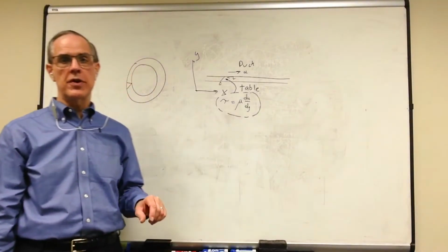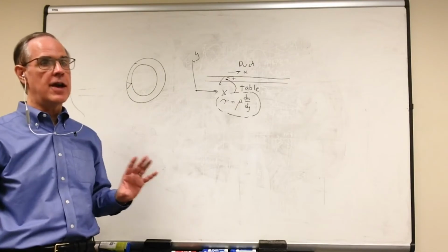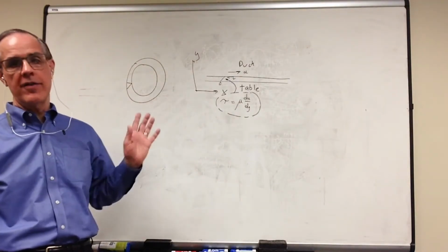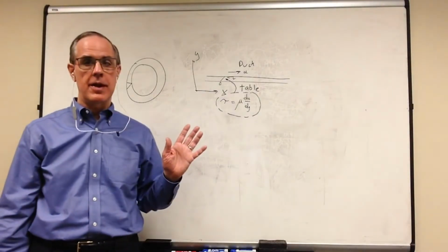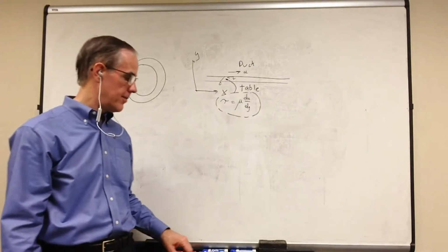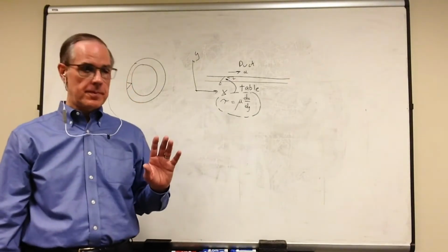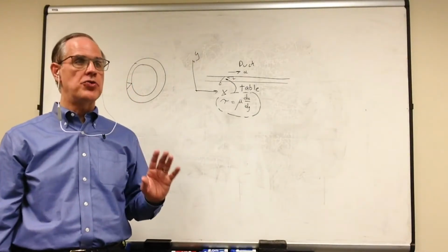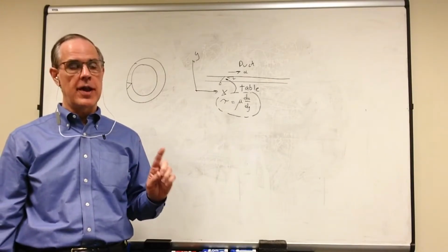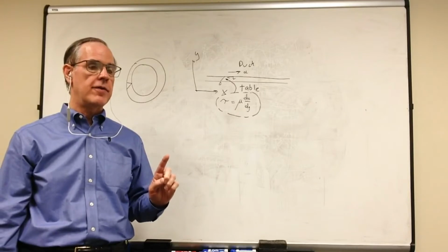If the fluid's viscosity becomes too thin, it breaks down, you will have metal-to-metal contact or metal-to-plastic contact or whatever you have, and in the end it will not be pretty. So that's why we have lubricants. So viscosity can be used in our favor, but it also comes with a price, and that price is energy consumption.